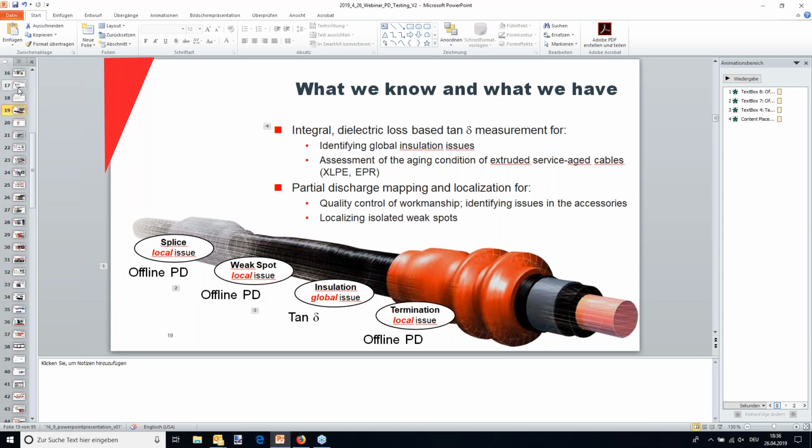Thank you. The next question is, as far as I know, obviously they know, I don't, PD trend value is important and not PD absolute value. So how can we test cable through PD absolute value? The absolute value is quite important because you calibrate the circuit, and that's the whole trick with this IEC circuit, that it is the only calibrated PD measurement.